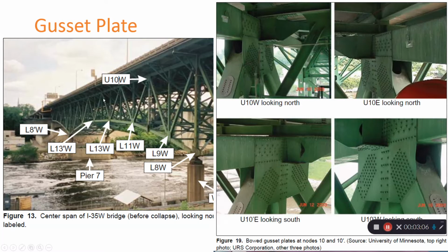On the day of the collapse, this bridge was undergoing roadway construction. About 2 hours 15 minutes before the collapse, there were equipment and aggregates stockpiled in the middle span of the bridge, very close to the critical cross-section of the bridge. That worsened the situation and eventually led to the collapse.